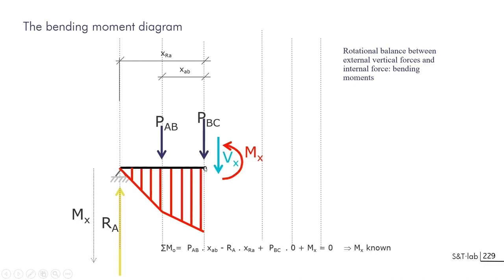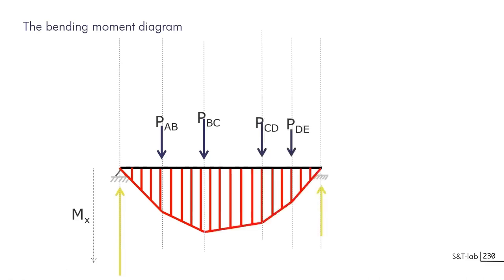You can see that you have this force having no lever arm, this force having one lever arm, XAB, and the third force, reaction force, that will have a lever arm, XRE. And so this system of force has to be equilibrated for bending. So you can write an equation in which you have bending that will be expressed with the lever arm of the two other forces. We'll see what is the corresponding graphic statics just later on.